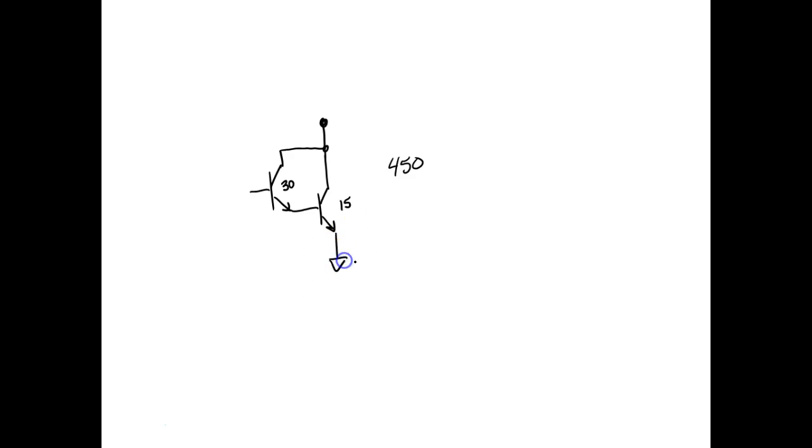So what they'll do is, like I said, we can look these up, but they sell these things, and it looks like a transistor because how many leads does it take? It takes 3 leads. So they could put this in a pack with just 3 leads coming out of it, and it looks like a transistor. But then when you start checking it with your meter, it doesn't measure 0.7 volts, it measures 1.4 volts, or right around there, you say, well, this is bad. You can't look at this junction right here. If I check between here and here, I'd measure 0.7. If I check between here and here, I'd measure 1.4. So it appears like it's bad.